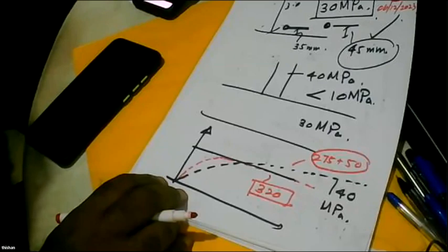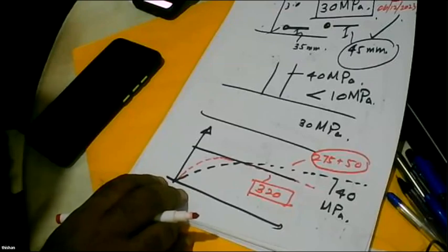You are creating a cover zone which is very dense, and when the cover zone is very dense, the pores are not connected, so you'll find the ingress of carbon dioxide into the concrete, with the reaction that we call carbonation, is very, very slow. Even after 100 years, you might still find the concrete is super strong and not affected at all because the carbonation depths are very small. So that's why the curing of concrete is extremely important.